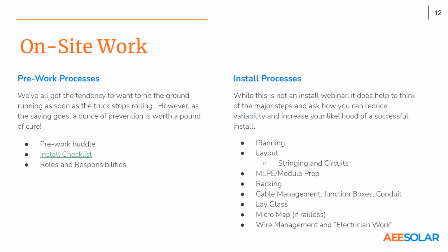Yeah, and it might save you some time on using raw cable or making your own connections. Anything like that's really helpful. And to go back to, I wanted to allude to this on Andrew's slide, that horrifying install picture. If you do a good plan on how you're going to string the array, you can avoid a ton of conduit. Conduit's not pleasant to work with in most instances, especially up on the roof. And if you can keep things tidy, that helps increase the feel good factor around aesthetics as well.